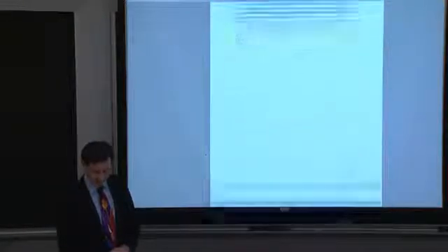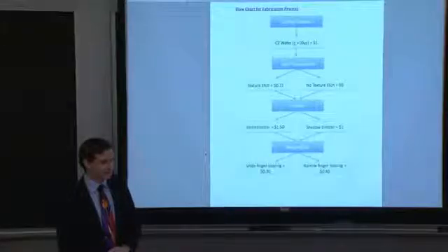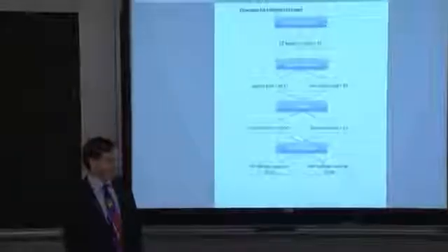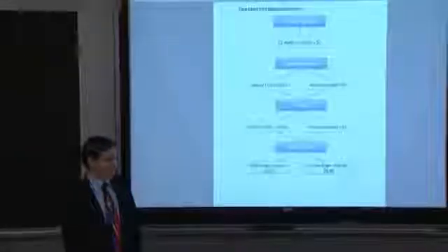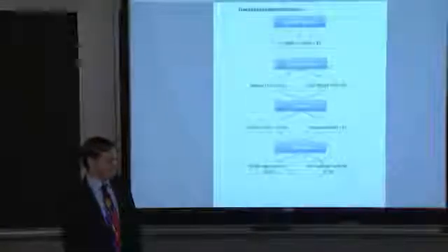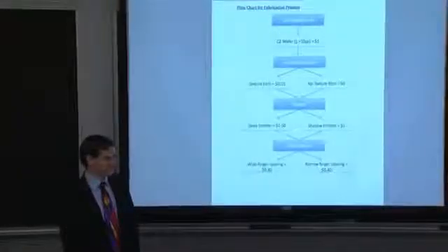Oh, the etching for the... For the etching, we gave a reference, and you can look that up. I did look that up, and for the other ones, is there? So that one you can get a pretty good estimate for. Okay. And for the other ones, is there going to be a single? I mean, in terms of shunting your device, it's really hard to predict the shunt resistance, but if you do shunt your device, you essentially ruin it. So I would just take that into account. This is meant to be, you're not going to get exact answers. But you can do your best to estimate series resistance from the finger spacing and your emitter thickness.